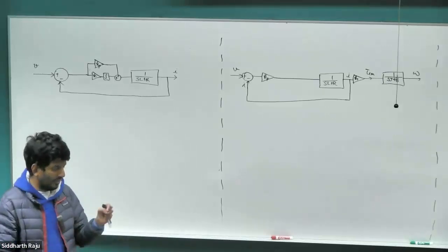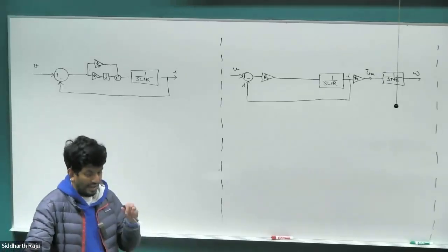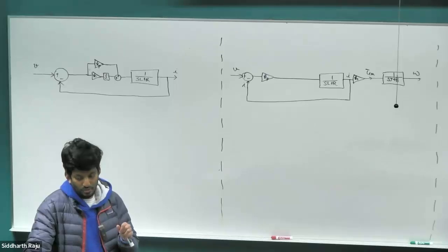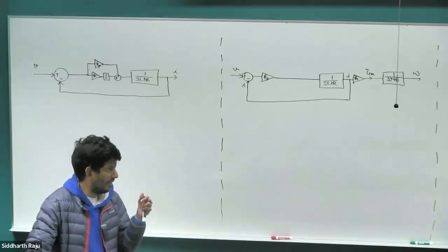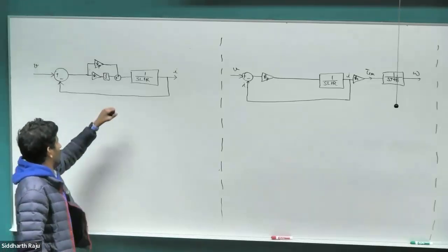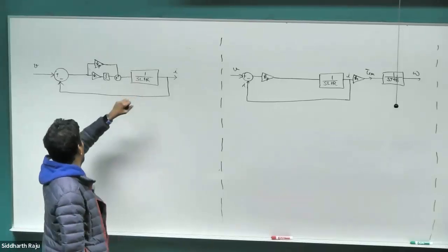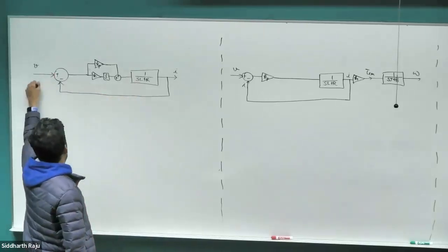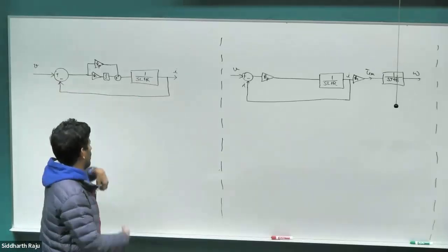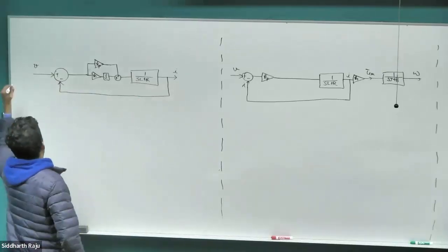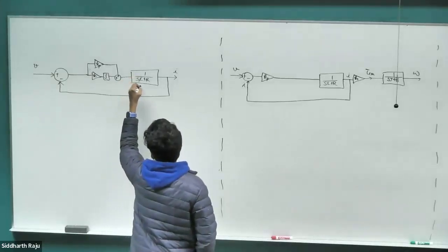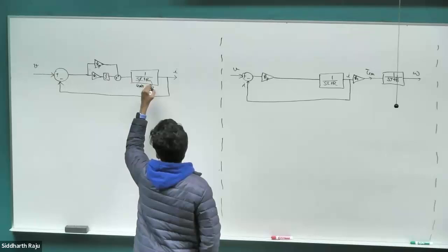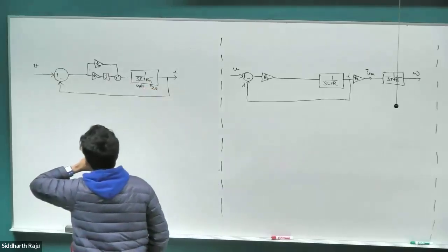There's one question in homework 7, the last question, which asks you to find the steady state error for a step input without an I controller. Let's say this is our electrical transfer function 1 by SL plus R, and we have a PI controller, some voltage reference, and some current feedback coming in. Let's put some values to it. Let's use the one from the lab, 4 millihenry, and 2 ohms.